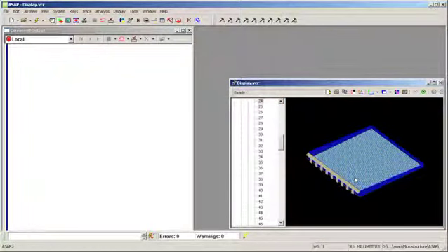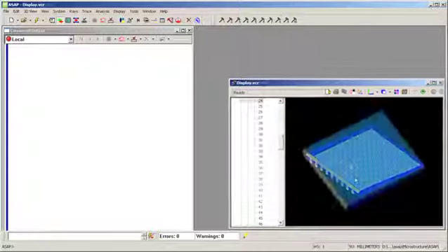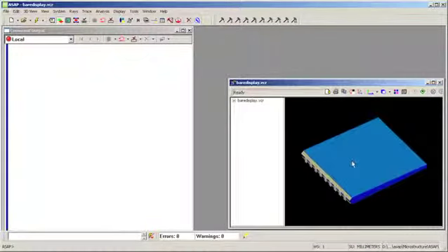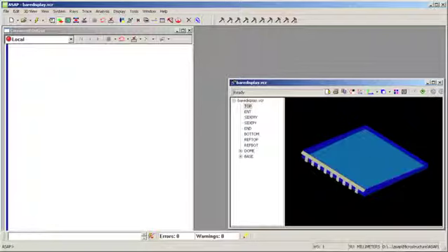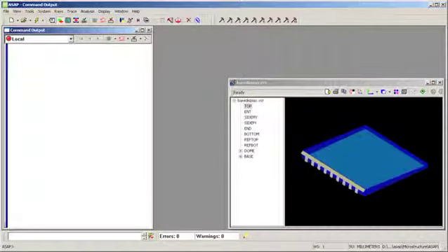Unit cell microstructure modeling in ASAP is done by constructing a single unit cell and telling ASAP to apply this unit cell over an entire object. Let's see how this works. Here is the same display we saw earlier, but without any bumps on the floor of the light guide. During a ray trace, we want ASAP to simulate the effects of the bumps, without actually having to place a large number of real bumps on the floor of the light guide. Here is how we do this.